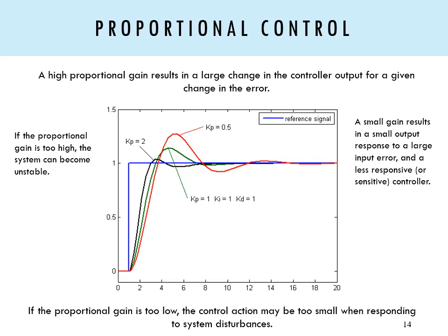The figure shows the process response curve of the proportional control with different controller gain values. The one in black has a considerably high controller gain, Kc equal to 2, whereas the red line process response curve has a considerably low controller gain, Kc equal to 0.5.